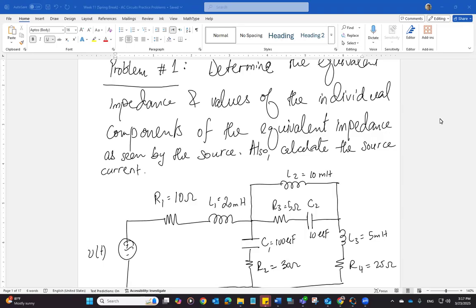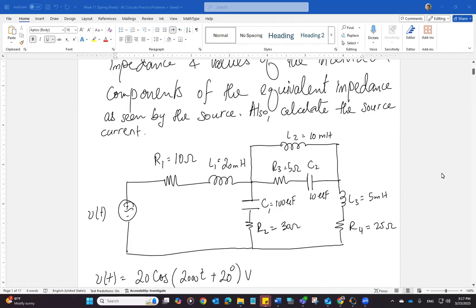MATLAB and Octave, as we've been doing, are the easiest way to solve things. Remember, not to analyze stuff. Analysis you still have to learn, and we've been learning the analysis for the last 10 weeks or so. But the main thing is to analyze the circuit properly, write down the equations, and then solve those equations using MATLAB or Octave. As we've been doing, we have our small functions that are written in MATLAB. And again, use those functions because they just make life very easy.